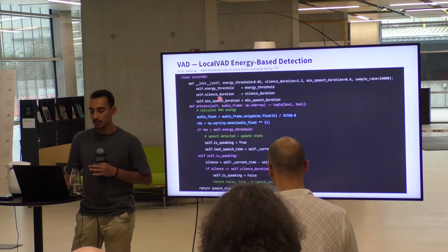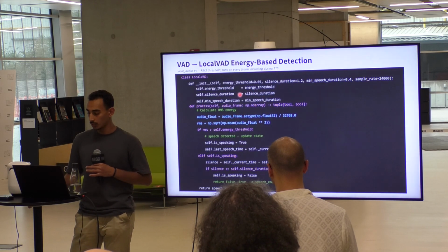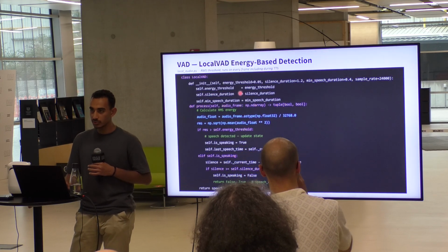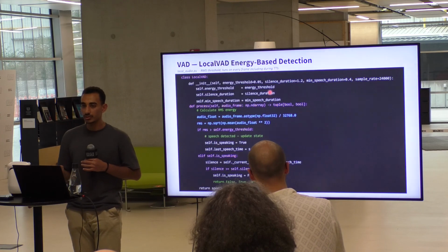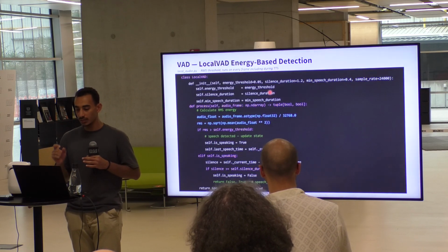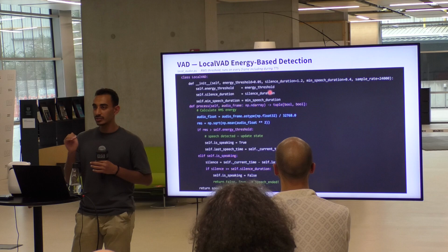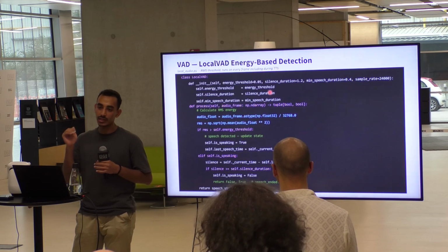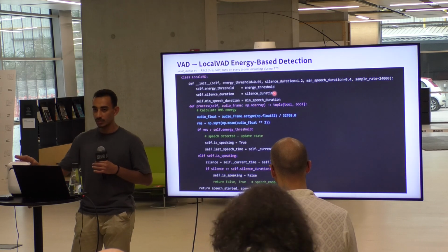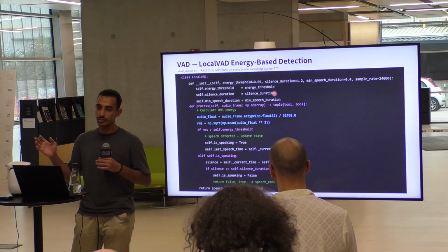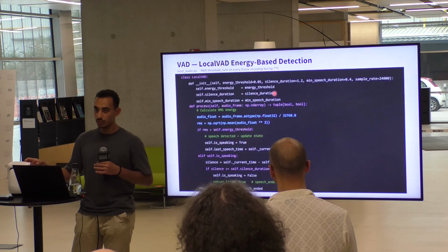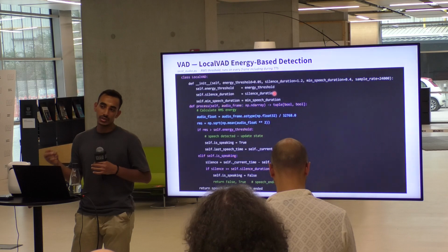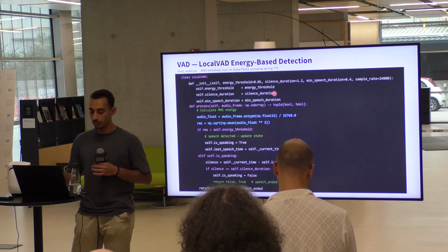We can see mainly here the first three variables, that this function predefines so that the Reachy can work properly. For example, here the energy threshold is responsible for Reachy not listening to every audio. It's gonna listen to the audio only if it reaches the predefined energy threshold and above. So in the makerspace, for example, there's a lot of noise, and not every noise is gonna fire the robot. It's gonna listen to the exact threshold and above, so you can know that there's someone talking to it.